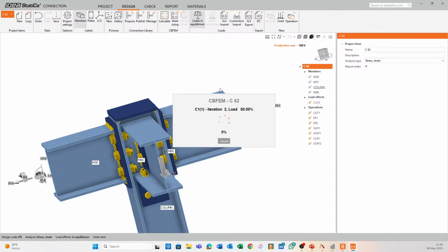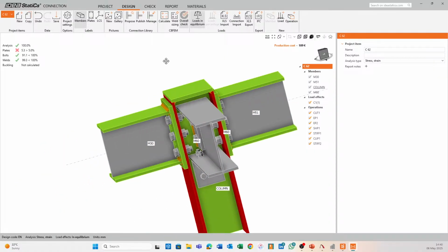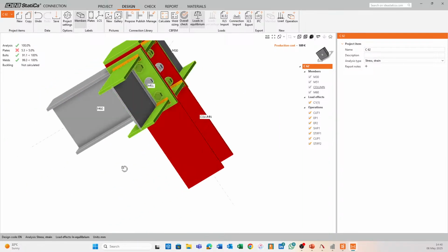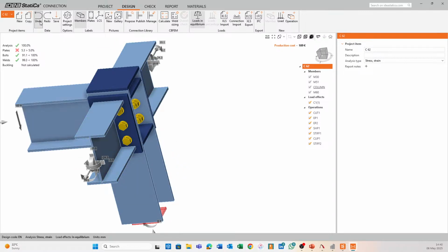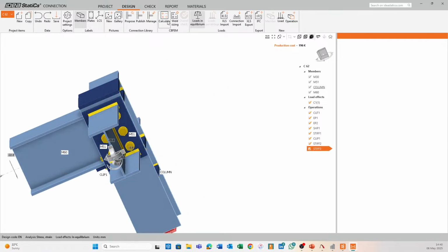And what's interesting to note is you can actually see the effect of stiffening up different parts of your connection, how that works in. Oh, look at that. How that works in to actually, as you stiffen up different points, that actually start taking away stress from less stiff elements, or elements that aren't as stiff. Okay, so I'm going to go back to undo. I'm going to reduce this guy maybe to even 5 mils. Okay, let's see. Okay, I might even reduce that guy even further.